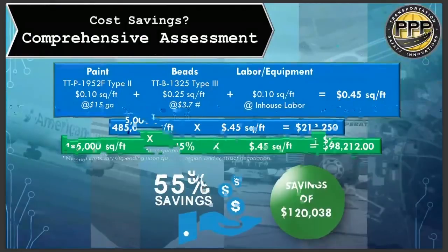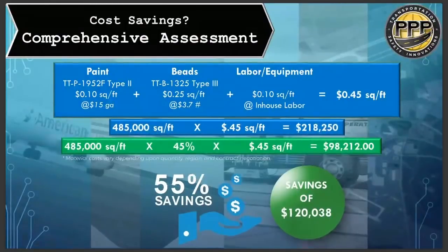They had to do an assessment to find out what they had to do, but we deal with FOD a lot of the time, something we don't see on the highways, and paint buildup is a serious FOD issue. You almost have to get down to a good substrate and a good application before you can start deferring a lot of the maintenance. But it's important to get out there and identify those areas and put them in the proper buckets.